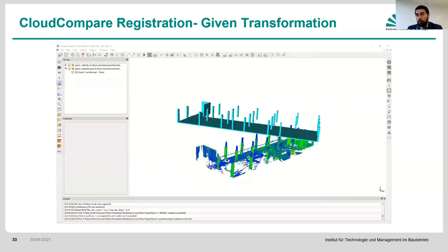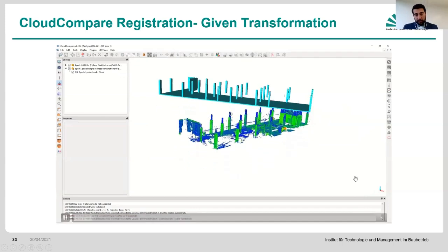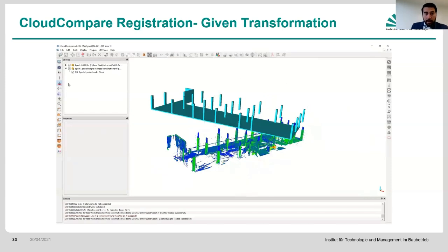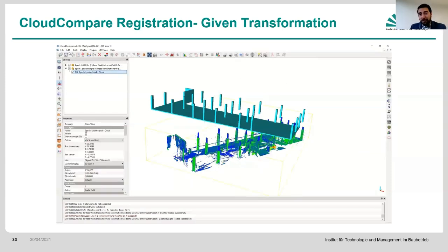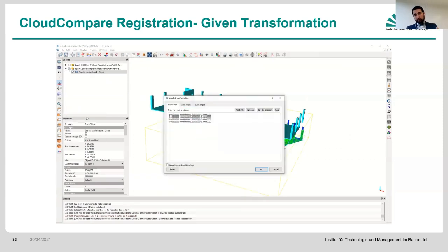And then here is basically where I want to also talk about the registration, because if you put both of these together, not only is that original model going to be larger because of the fact that when it came in, it came from inches and now it's in centimeters and meters, you now have to perform the rigid body transformation in order to transform these two coordinate systems together, as I explained there. Now, I've made your lives a little bit easier because I wanted you not to necessarily focus on creating your own registration, but to perform the registration the way that it is.